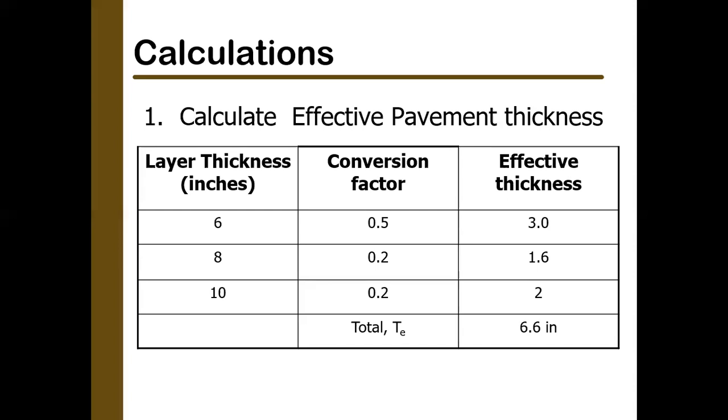So, as I was discussing in the demerits, sometimes your overlay design may not be very economical because we have taken some factors from visual observations. So this is a risk, but at the same time, you may have an overestimated design, which may also be good to consider the safety factor, but it will not be economical.